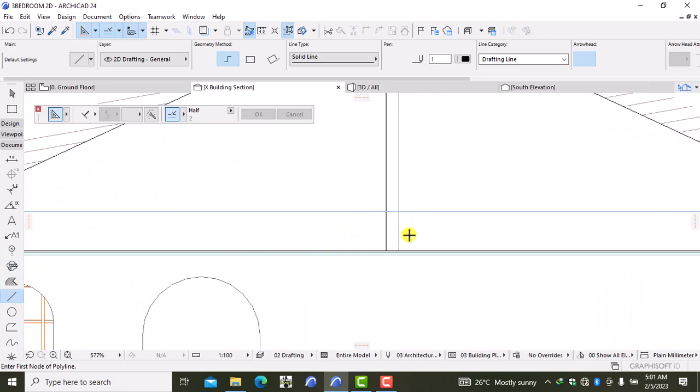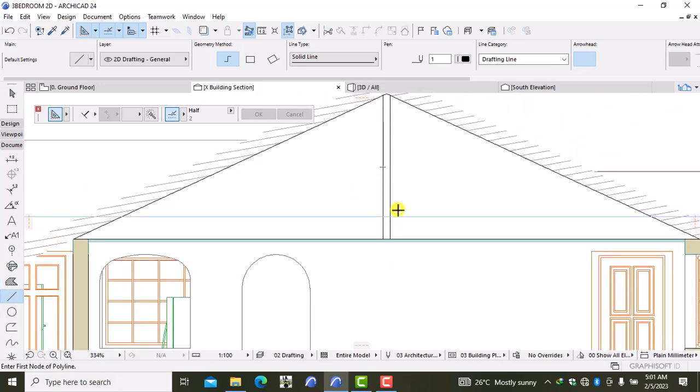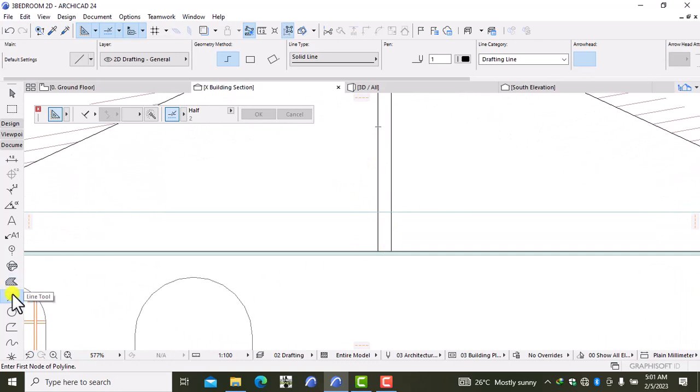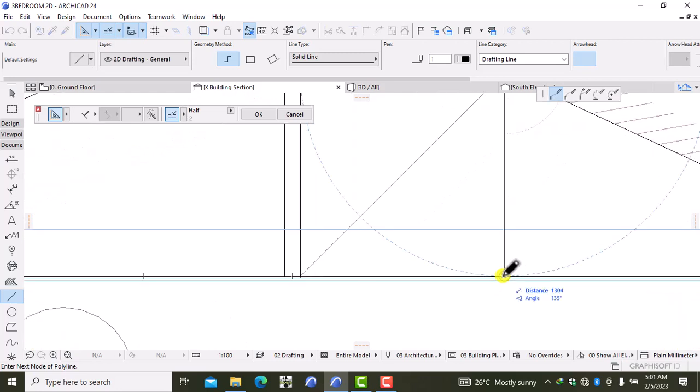So I can take it to the line. This is normally referred to as the king post. For the king post, you can use wood of size maybe 3 by 2 inches and such. So I want to orient this at an angle of 45, and then just drop this up to that point where we had this line.